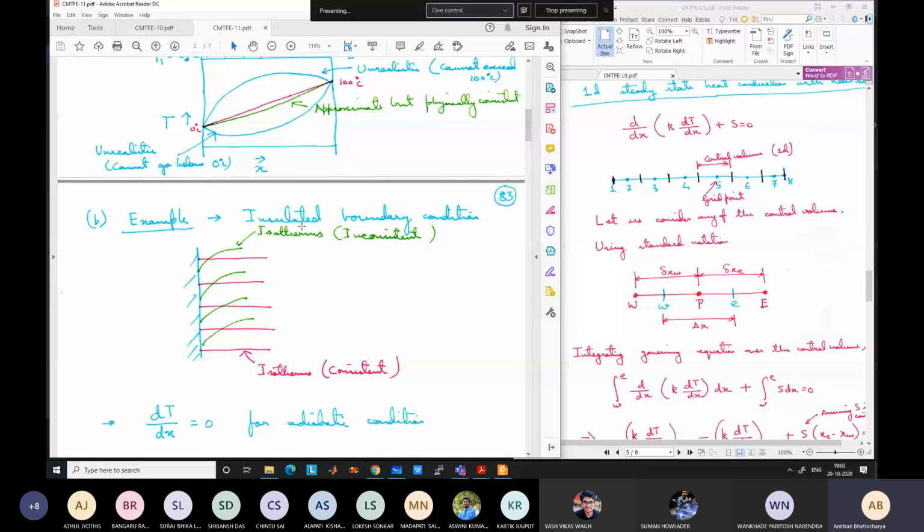Simulation is based on the assumptions we take. So if you assume that the interface is adiabatic in the simulation, it has to be perpendicular. Because you are assuming that it is adiabatic, where would the heat flux at the boundary come from? It cannot be there. Already you assumed that it is adiabatic, so in the simulation there cannot be any heat flux at the boundary, right? Simulation is not an experiment. Although you are assuming something, there is no way leakage can occur, because it's a mathematical problem. It's not a real-life problem.